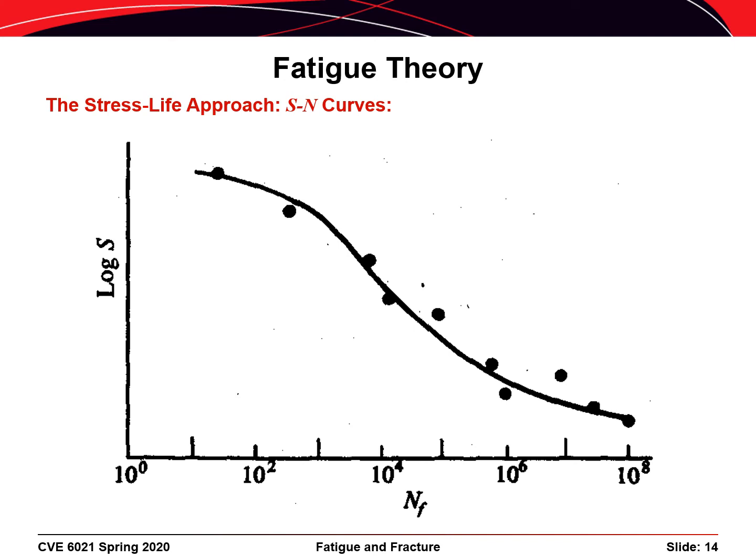If you have enough experiments on the same detail at different stress ranges, then a curve can be plotted for that detail. These curves are called SN curves, and they are typically plotted on semi-log or log-log charts. SN data typically shows less variability at shorter lives and greater variability at longer lives. And the variability in data can range from less than a factor of 2 to 1 or 2 orders of magnitude. Most materials have a continuously sloping SN curve like the one shown here.